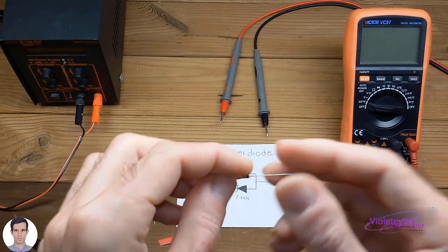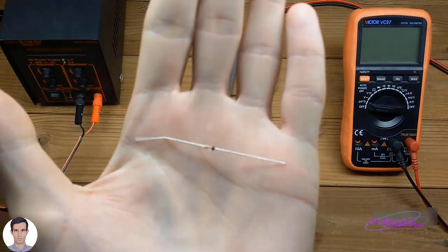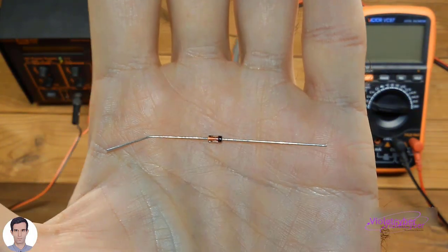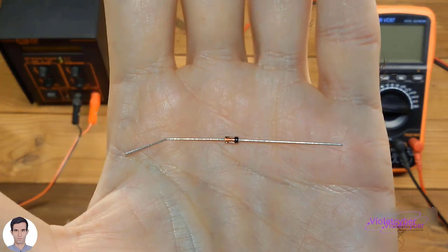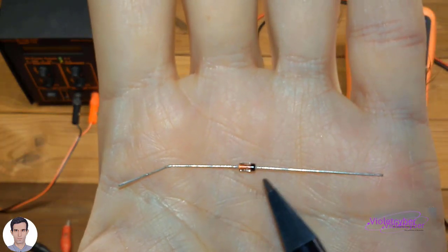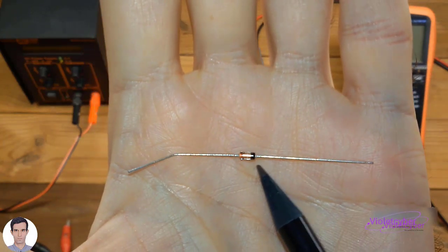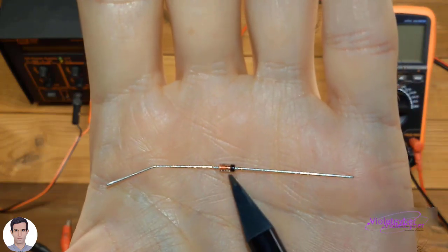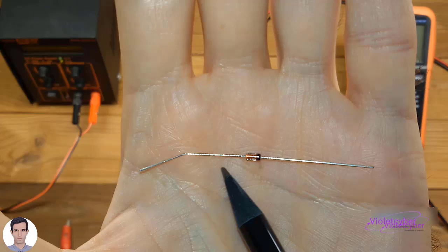As you can see here, a Zener diode looks similar to regular diodes, with the difference that it has a glass body. It is usually brown in color, and is available in various sizes and wattages in the market. A Zener diode, like a regular diode, has a cathode and an anode side. The cathode side is marked with a black or blue stripe. In some diodes, this stripe is black, like in this diode, and in others it is blue. In any case, the cathode side of Zener diodes is identified by such a stripe.